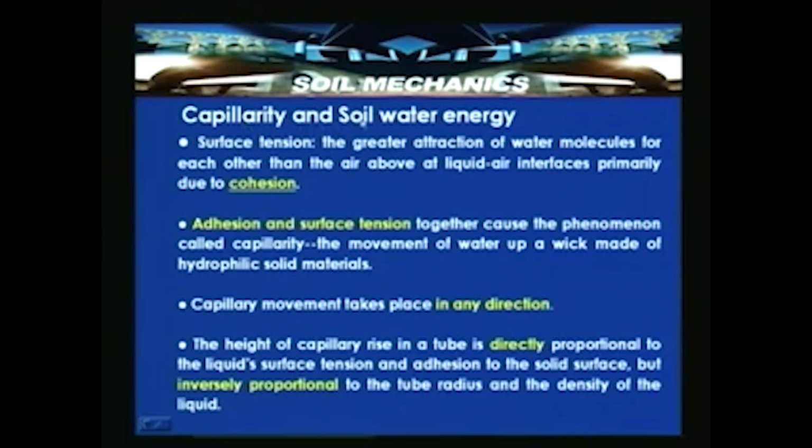So, capillarity and soil water energy: the surface tension, the greater attraction of water molecules for each other than the air above at a liquid-air interface, primarily due to that cohesion. So, adhesion and surface tension together cause the phenomenon called capillarity. That is what we have discussed. Adhesion and surface tension together cause this phenomenon which can actually draw the water against gravity and can be kept within the pore spaces.